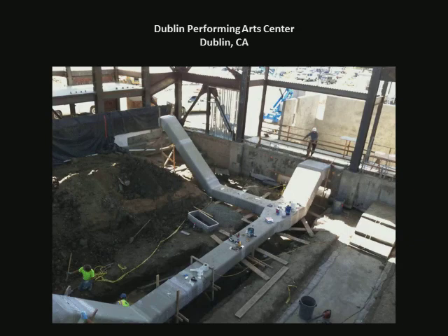That means when it shows up from the factory, not only are the fittings, reducers, taps, and elbows put on to the largest extent possible for shipping limitations, but the insulation is inside as well. We have an outer layer of fiberglass, a middle layer of 1-inch polyurethane foam insulation, and an inner layer of fiberglass protecting that insulation from any moisture inside the duct or any acidic conditions outside the duct.